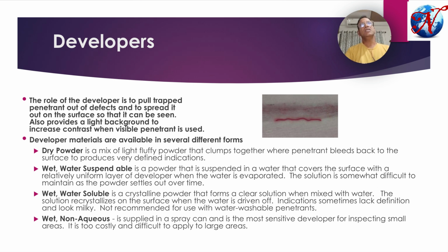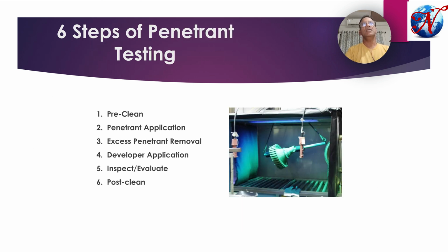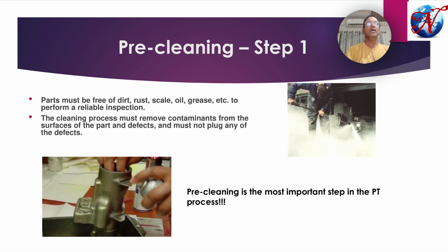So in gist, we can say in the penetrant test there are 6 steps: pre-clean, application of penetrant, excess penetrant remover, developer application, inspection, and then post-clean. Pre-cleaning is the most fundamental and most important step of liquid penetrant testing.